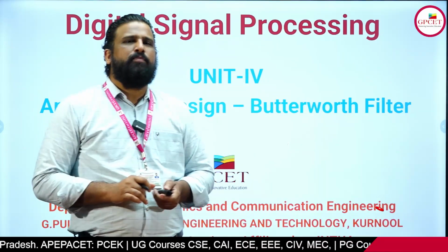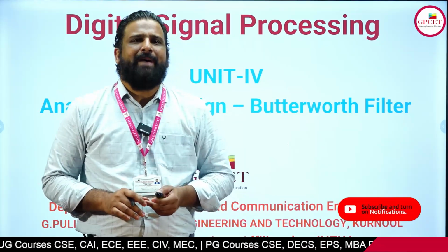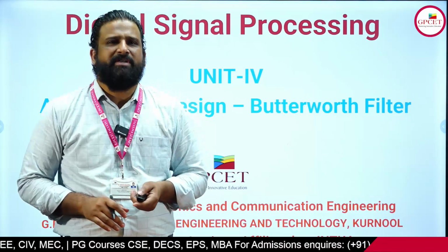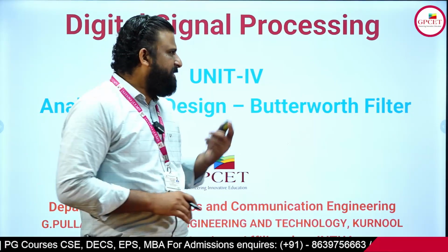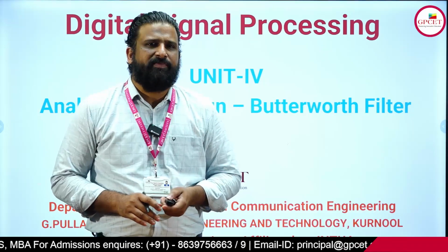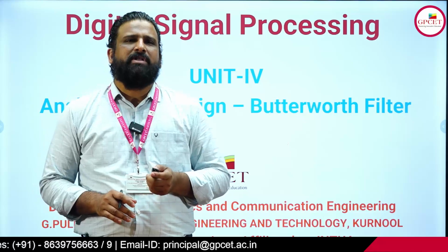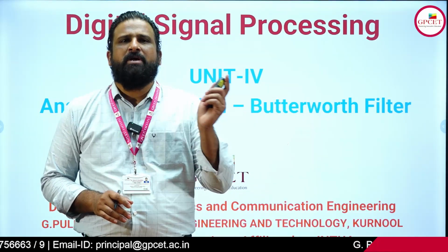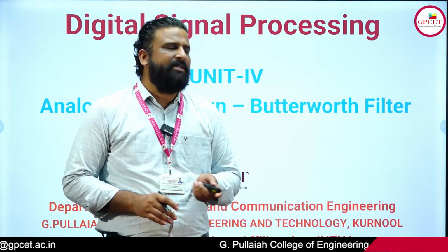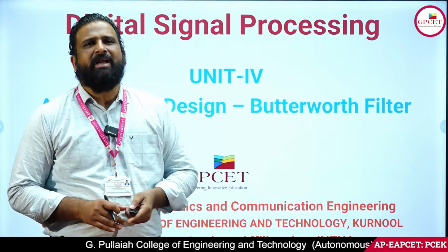Based on that point, let me discuss how the analog transformation happens first, and then after transforming into the analog form, how it is converted into the digital form. We will see that in this session. For that, we are going to study two techniques, which are the Butterworth filter and the Chebyshev filter. The conversion takes place by first designing the analog filter, then converting it into digital with the help of these techniques.